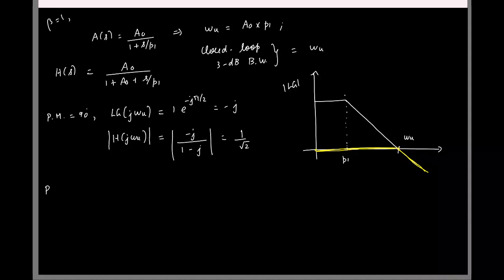So now let us say I have a second order system where I have a phase margin of 45 degrees after doing the compensation. So what is the loop gain evaluated at unity gain frequency? Gain is 1 or the magnitude is 1. What is the phase? Minus 135. Okay, phase is always dropping, so e power minus j 3 pi by 4. And again, if you actually find out what is the magnitude of omega u, it will actually be greater than 1. Okay, it's just a complex number, I don't want to do that here.